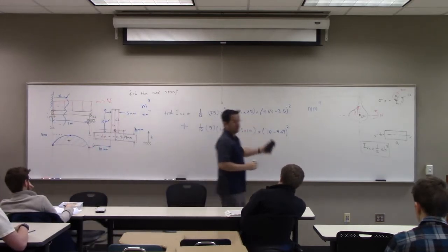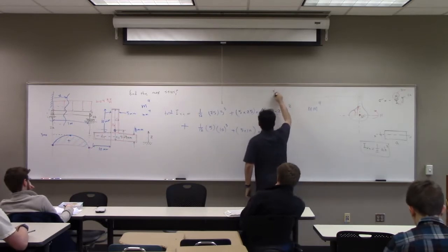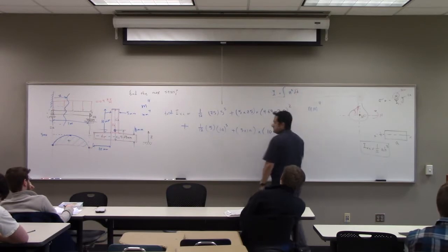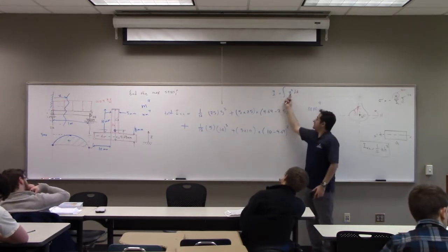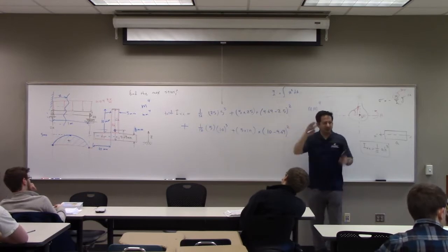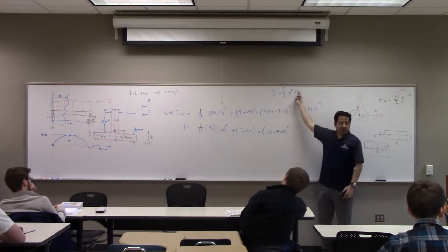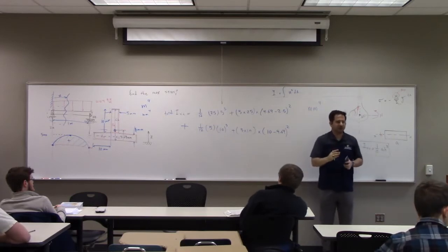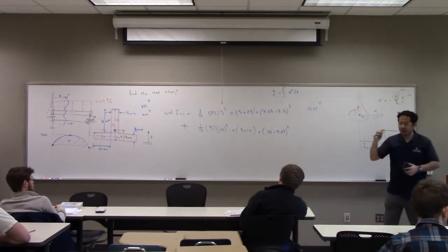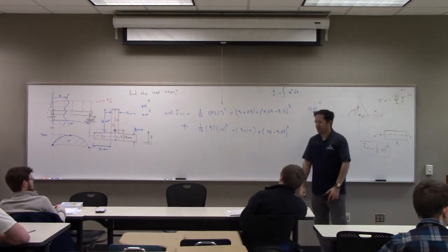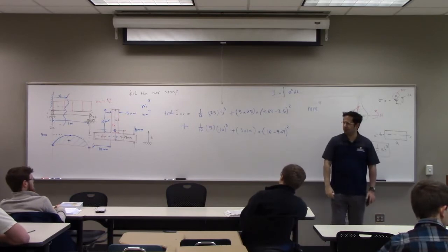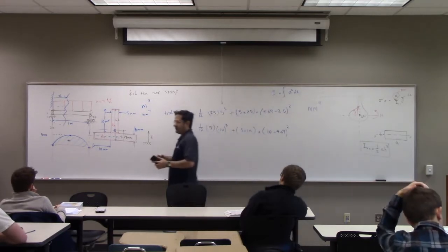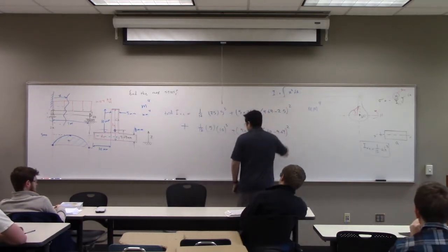If you go back to the definition, moment of inertia was the integral of x squared dA. So what's the dimension of x? Let's say meter. So you have meter squared here, and area is what? Meter squared. So meter squared times meter squared is to the power 4. That's the 4 that you see there, but sometimes we get confused. We say, well, area was second, why did you get 4? Or vice versa. That's because of the definition of moment of inertia.